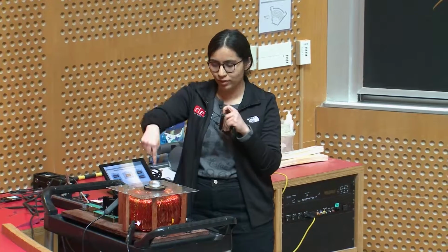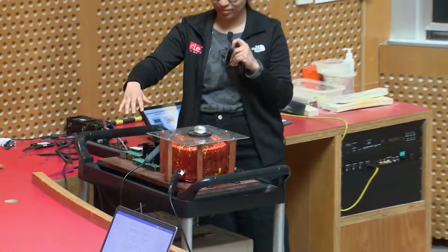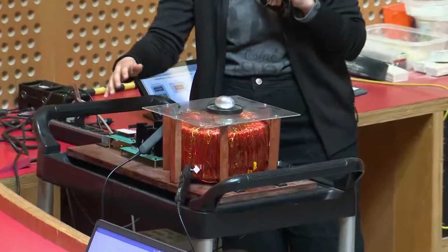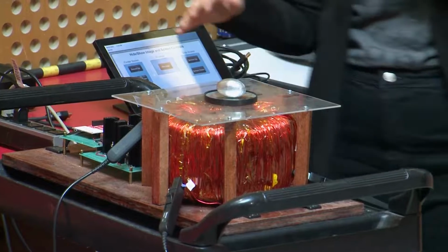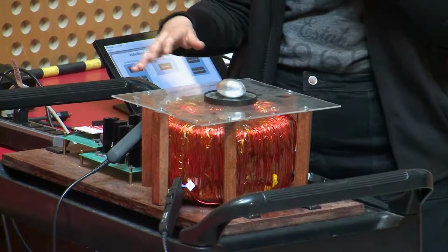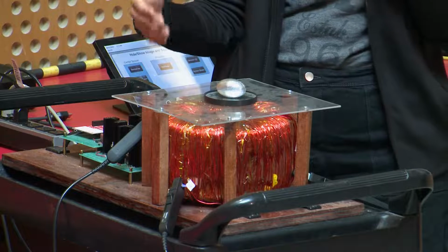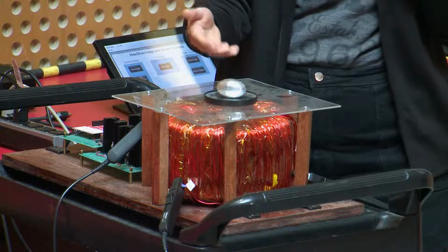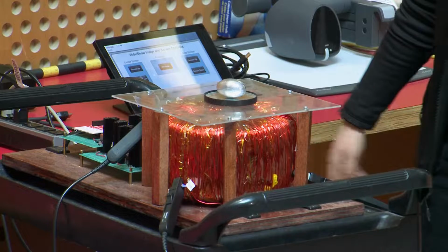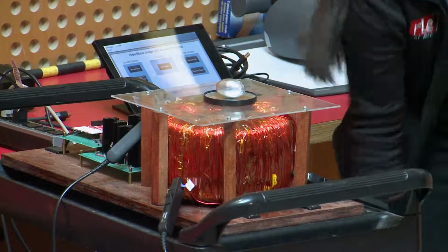For our rotor, we're gonna use this metal egg. And then on this side, we have our three-phase inverter with 6 switches, and this is our gating circuit. So what's gonna happen is that we're going to create some rotating magnetic field using our stator, and then that's going to induce some eddy currents in our rotor, that is our egg, and then it's going to force the egg to spin. So let's start by trying to slowly increase the bus voltage and see what's going to happen.